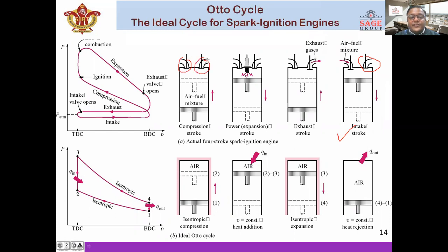And when the piston is at the topmost condition, and the spark plug is operating, both valves are closed. The sparking is done when the piston is at the topmost condition, and the sparking of the mixture is taking place, where the combustion process is initiated. The combustion process will be initiated and the force of the gases will move the piston from TDC to BDC.